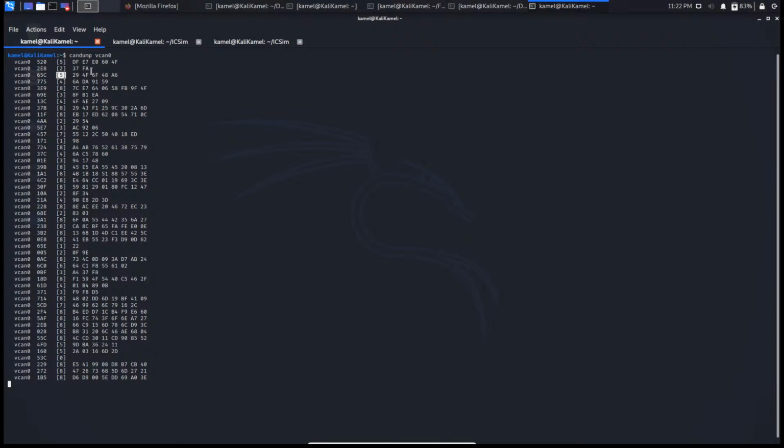The arbitration ID is used to identify what type of real-world information is stored within this data. Because obviously inside a car, if you look at the electrical signals and you convert them into hexadecimal, they will look something like this. But to the ECUs actually processing this data and using it to operate the vehicle, there's hidden meaning behind all of this data. This has to do with CAN signals and database types, etc. We can't go all the way into that today because we do have some more key features we have to talk about. But knowing that this hexadecimal data gets translated when it's received by an ECU is an important step in learning how to reverse engineer CAN data. So there's not that much information that we can see here due to the fact that there's no timing information, right?